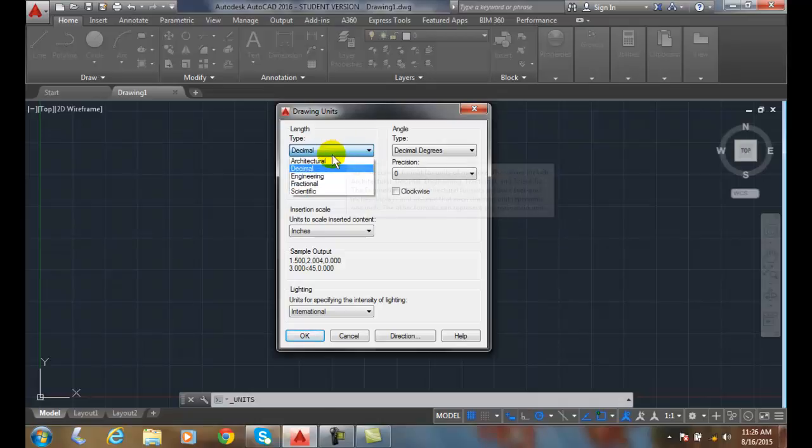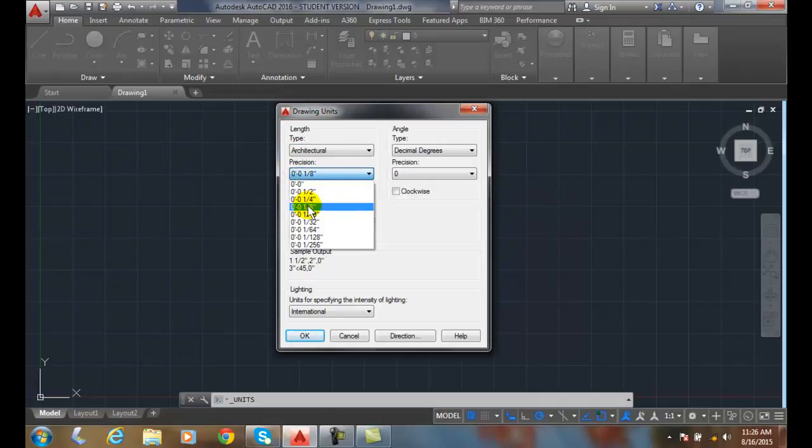So if I was building your house and I go to architecture, I want a precision of about 1/8 inch. No carpenter is going to measure to 1/128 of an inch. You can't find that on your ruler. And 2x4s are not that straight, and so they generally measure to the nearest 1/8 of an inch.